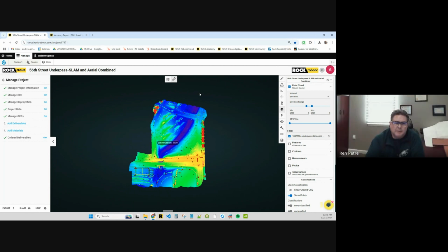Okay. My traditional workflow is to set up the RS3, turn it on, let it go, get the 350 all hooked up, get the LiDAR on it, do the flight, and let everything assume its own data. And sometimes it comes in within 3 feet or 15 feet of where it's supposed to. Then, luckily, with all the equipment we have, we'll shoot everything with the GPS. We'll go around sometimes twice, double shoot everything and take all the averages we can to get it real tight. Or if it's open enough, we'll even set up with the robot and shoot, and then we're under 100th for your control. It really tightens things up a little better that way.